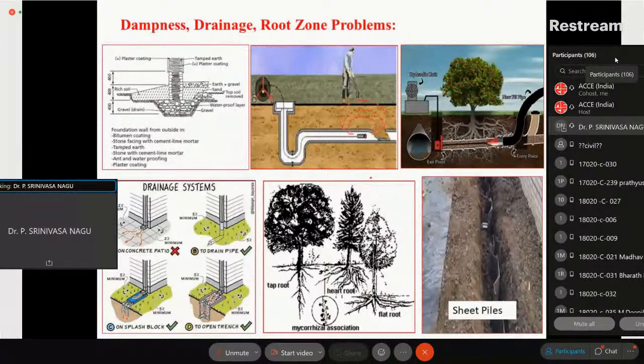So dampness involves ingress of moisture. So why should you allow it to come? Why is it coming? It may be coming against gravity, where water flows upward. That is what we call capillarity effect. All these capillarity effects are more problematic due to the wet conditions around the foundations. So you have to treat the foundations properly such that water will not stagnate there.